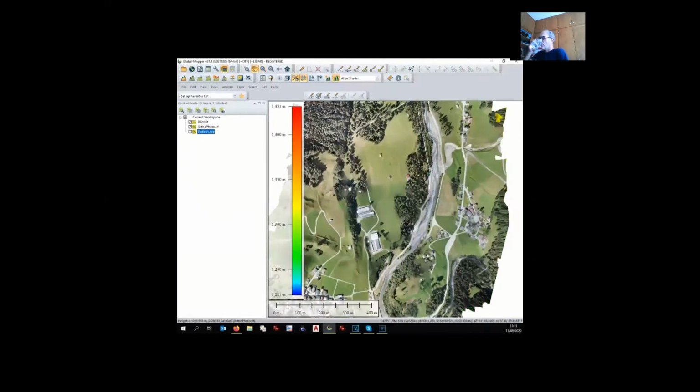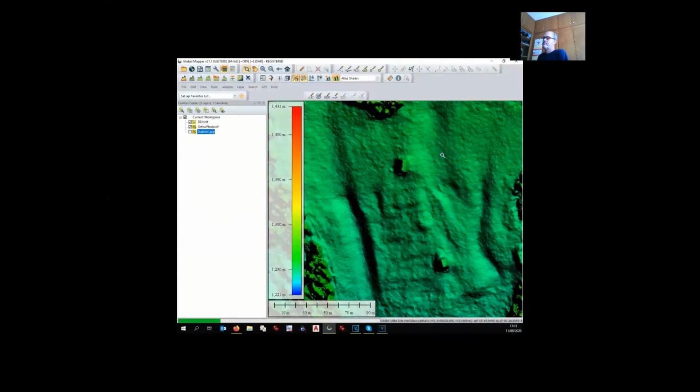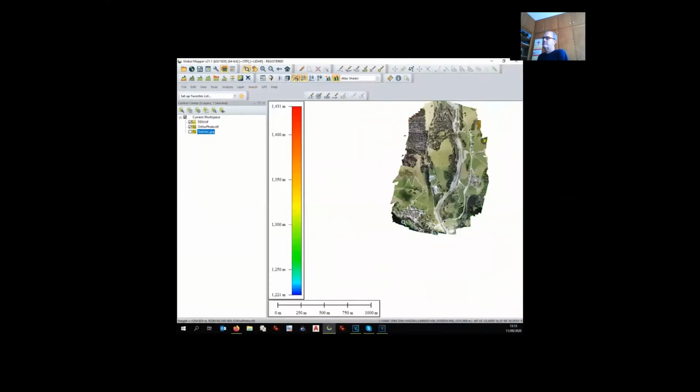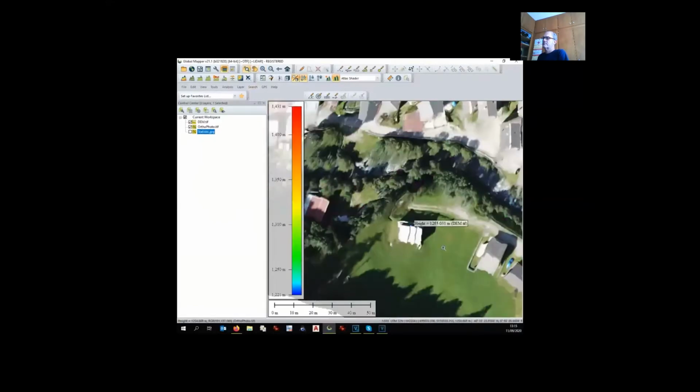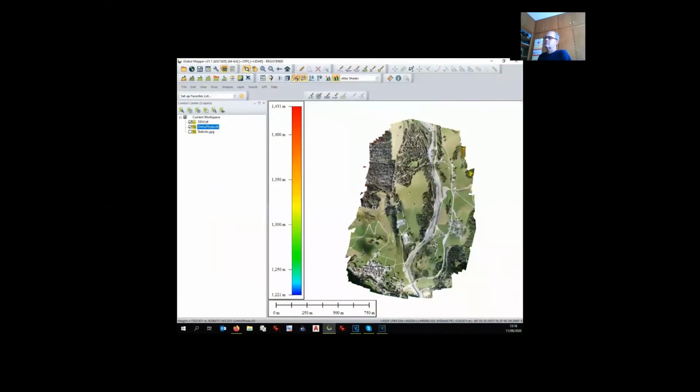If we look at the imagery of this part, for example, this house here in the middle, where we have high overlapping, the building is nice, it's square, and looks very, very real. If you go into the border, where we have bad overlapping, you can see pictures are much worse. You cannot really use this type of information. That's why it's important to crop out the good part of the imagery and to delete or not consider the bad part of the imagery.